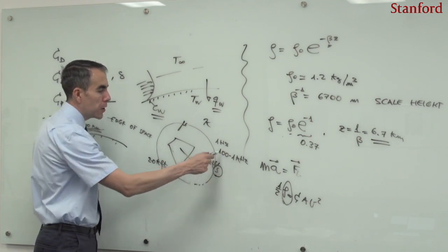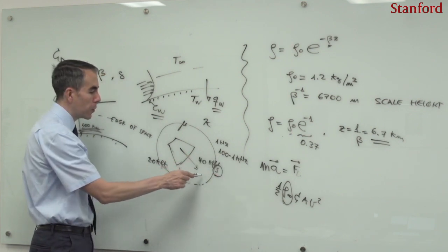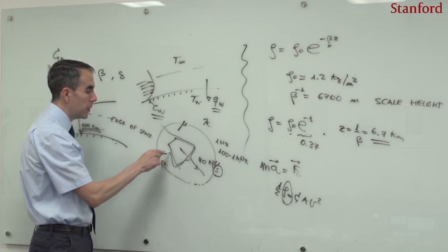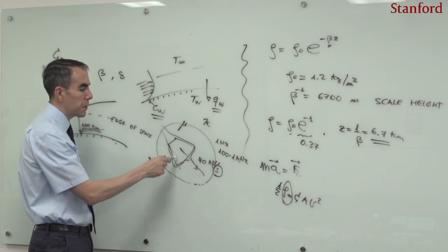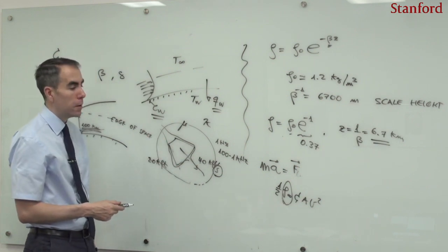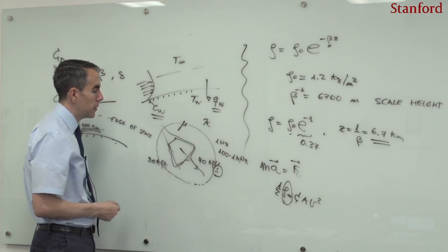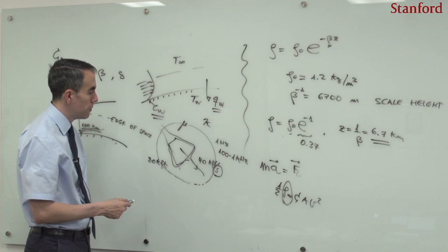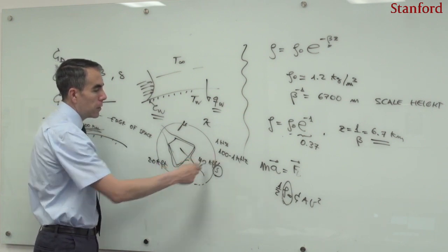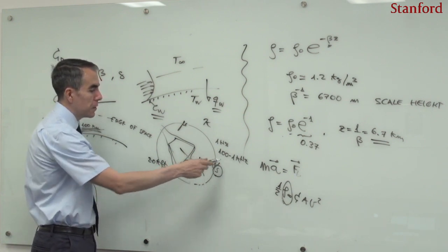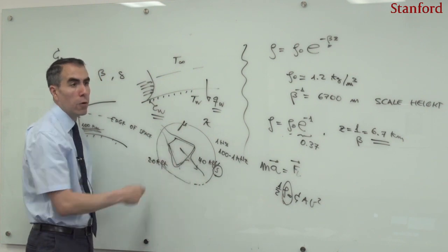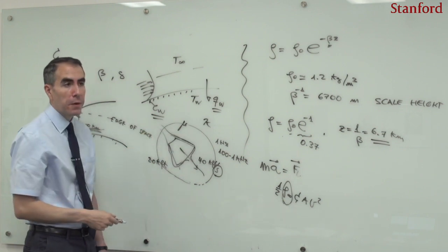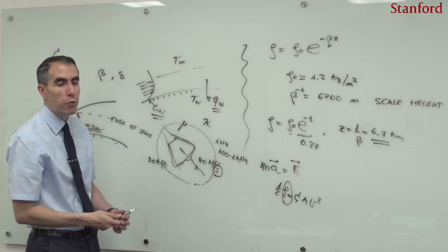This frequency or that characteristic time needs to be compared with the characteristic flow residence time around the capsule. And this characteristic residence time around the capsule tends to be of the order of 10 to 100 microseconds. So this is to say that these frequencies can get to compete with the residence time around the spacecraft. So one needs to be careful with those atmospheric fluctuations.